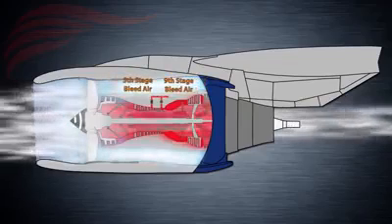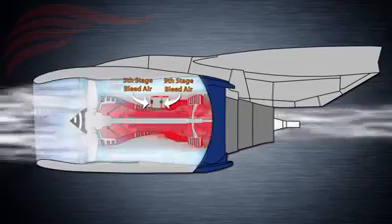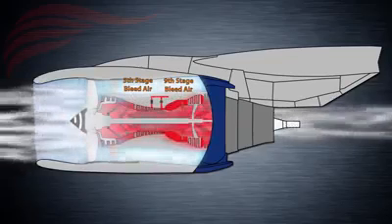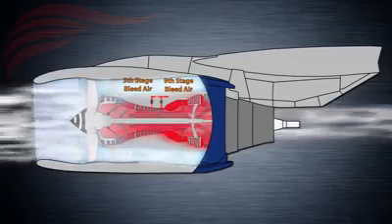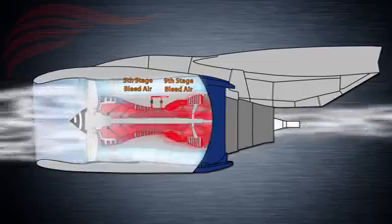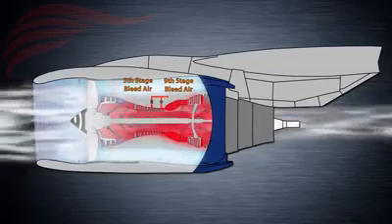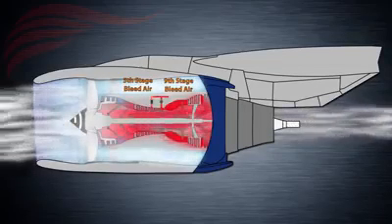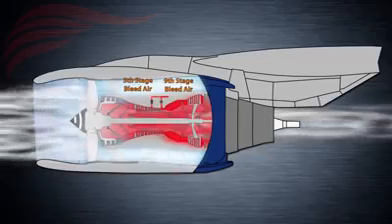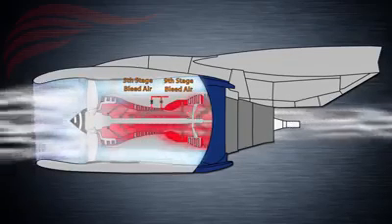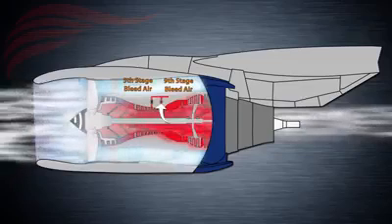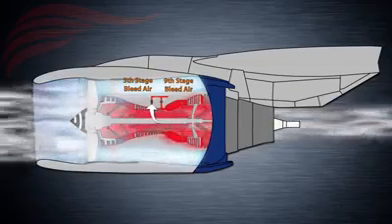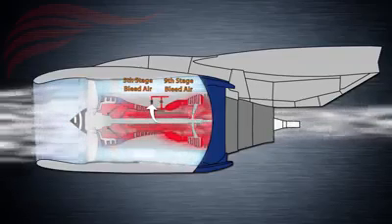Technically, bleed air is extracted from the 5th and 9th stages of the engine high pressure compressors. In some engine scenarios, such as when there's a high pneumatic demand from the aircraft systems and the engine is running at idle power, bleed air from the 5th stage is not enough to supply the required demand. In this case, the pneumatic system commands bleed air extraction from the 9th stage of compression automatically by means of a high stage valve. Each stage of compression has a check valve that controls the flow of air between the compressors and the engine bleed air manifold.